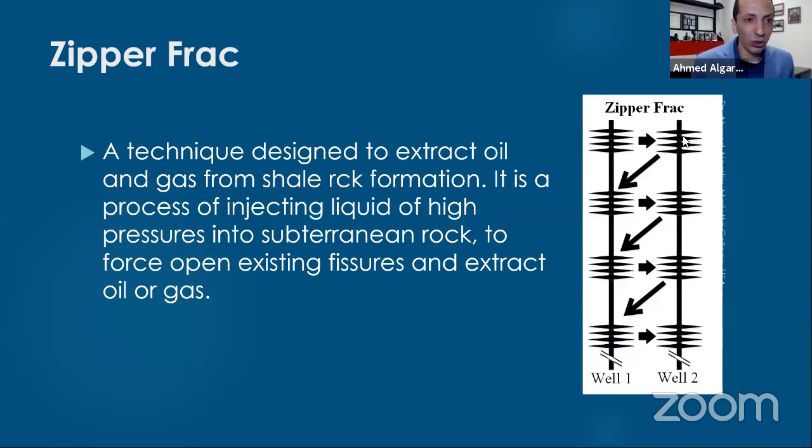So you must use fresh water with exact specifications. Whenever we get fresh water in Egypt, let's say in a location for Khalda Petroleum Company, we need to test that water. We check how much phosphate, how much iron, how much whatever, and we decide if it is okay to use it in fracking, or we decline and reject that tanker. If you use seawater or salt water, it will damage your formation and you will not produce anything. Or if we are optimistic, we will produce very little.